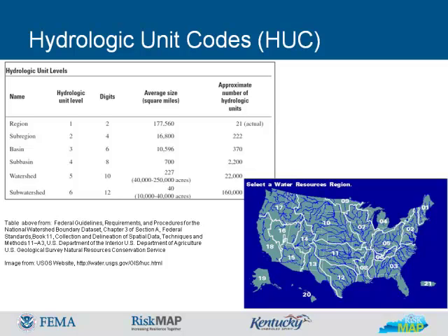These 378 hydrologic accounting units are nested within or can be equivalent to the subregions. The fourth level of classification is a cataloging unit, the smallest element in the hierarchy of hydrologic units. A cataloging unit is a geographic area representing part of all of the surface drainage basin, a combination of drainage basins, or a distinct hydrologic feature. These units subdivide the subregions and accounting units into smaller areas.